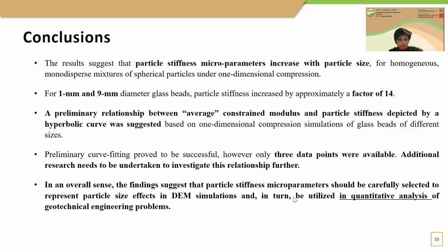As for the overall conclusion of the study, the results suggested that the particle stiffness microparameter increases with the particle size. For our study of 1 millimeter and 9 millimeter glass beads, we found an increase by a factor of 14 between the parameters. So we derived the preliminary relationship.